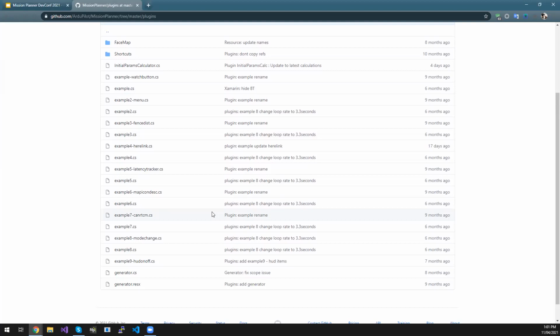Yep. So it's very similar. Like I said, the IronPython is just Python. It's evaluated at runtime effectively, whereas this is technically compiled at runtime. So unlike IronPython, you couldn't change it and rerun it, change it, rerun it. This here, it's more as Mission Planner starts up, so you can't change the code and then just expect it to change. You'd have to actually restart Mission Planner between your debugging sessions. There are other options about just compiling it into Mission Planner if that's your preferred choice in the first place. But this is just an example of how to do it at runtime.